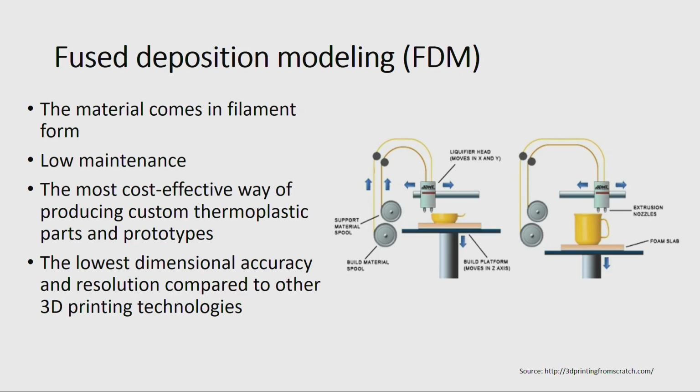While making a 3D printable object, the 3D printer may require some support. Suppose here we are making a cup, so the cup handle is something which comes out of the main body. While printing, the 3D printer may require some support structure to support the handle being made. That is why this 3D printer is using a support material.